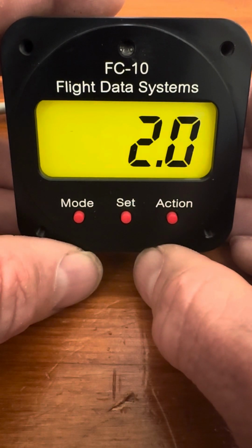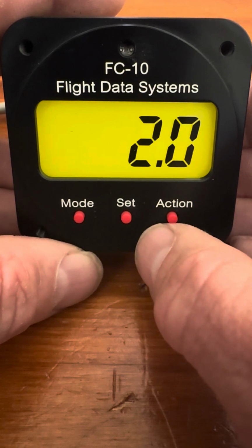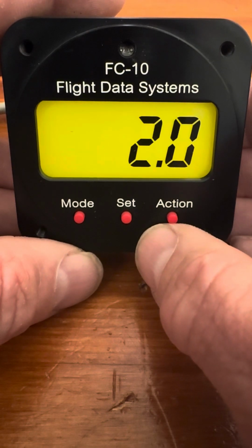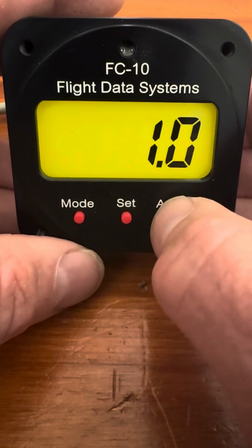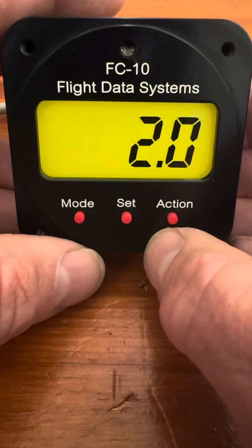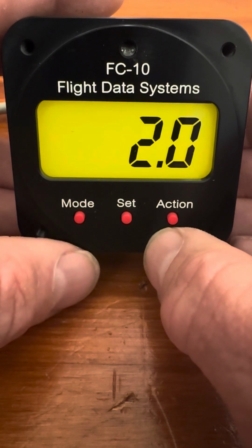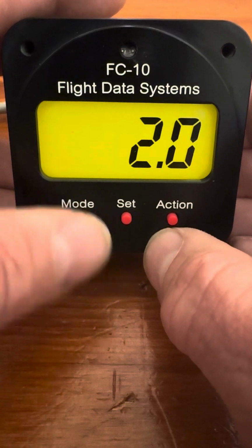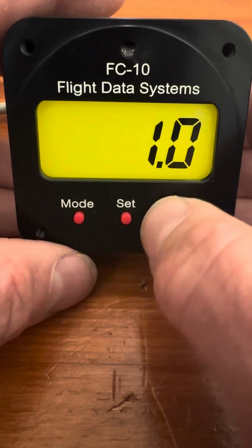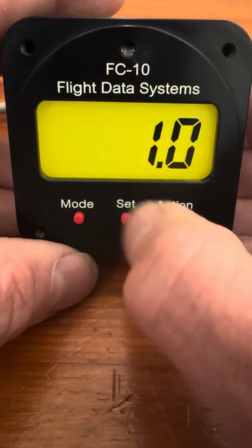Moving on to efficiency, that corresponds to the number of engines in your aircraft. So if you have a single engine plane, you would decrease that to 1. If you have a twin, you would set it at 2. Now, if you have a fuel return transducer in your single engine installation, you would also use 1 because this is always the number of engines. So we'll leave that at 1.